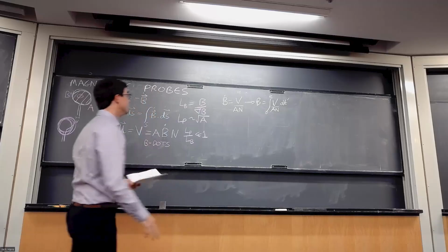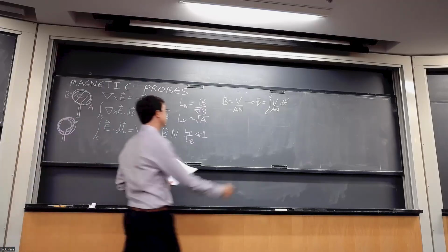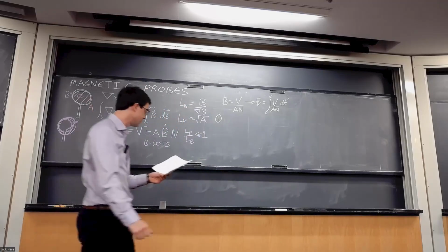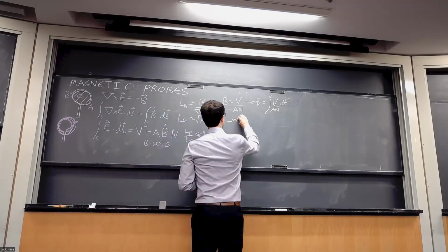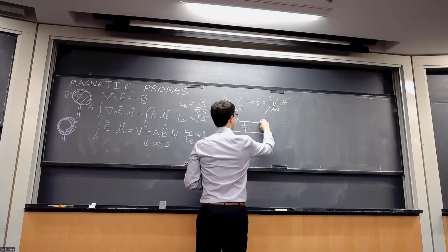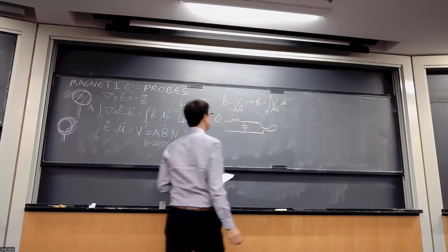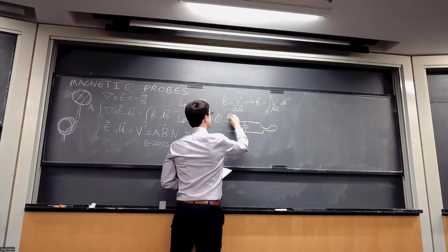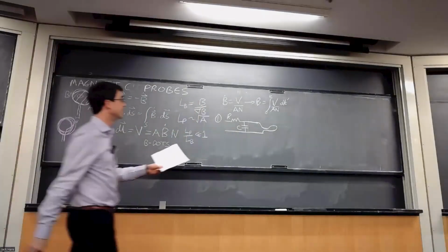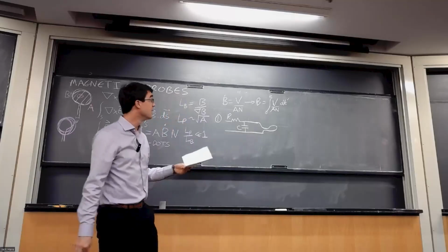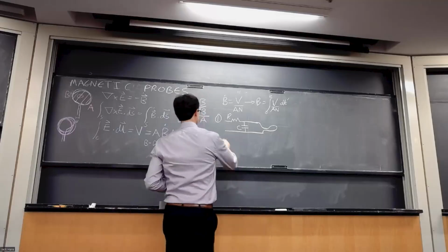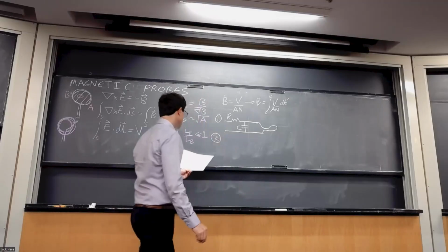Okay, and there are a few ways to do this. Back in the day, you might want to try and do this automatically, because doing this numerically may be computationally expensive. You could do this passively. You could have some sort of RC type filter. Those of you who know your analog electronics would recognize something like this, where we've got our B dot loop at the end there, and we've got some resistance and some capacitance. And this forms a low pass filter, which, depending on the frequency of your signal, will passively integrate it up. So that's very simple to build. If you're trying to put 1,000 B dot probes around your Tokamak, you might think that this is a nice solution. If you want something a little bit more fancy, you can do this with an op-amp.